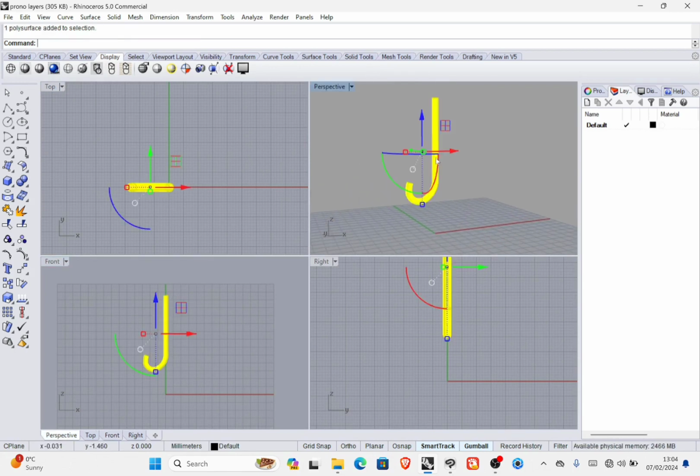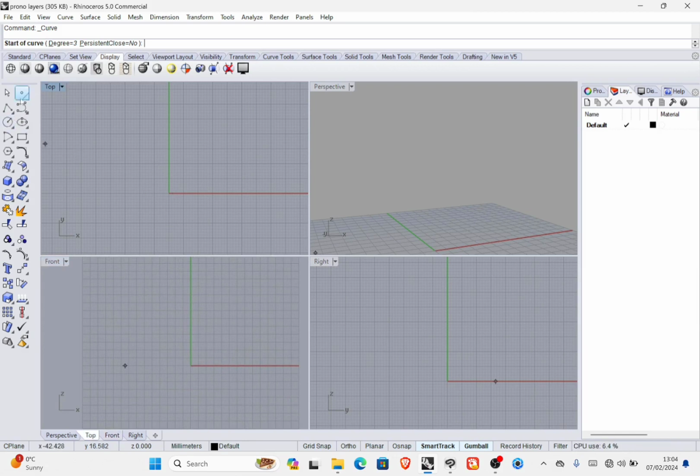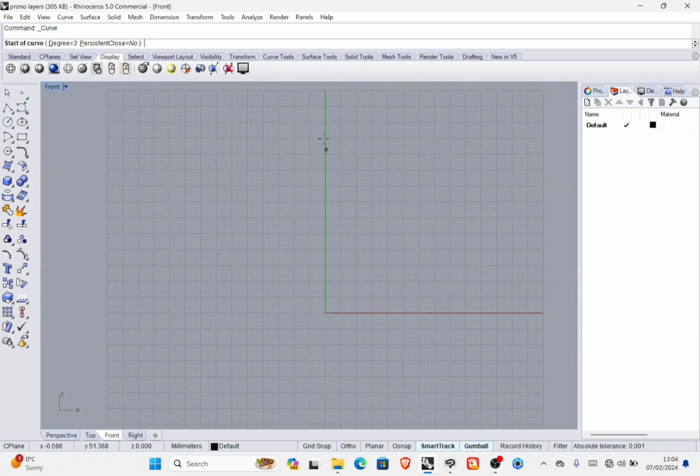So that's how to achieve a bend in Rhino. It's just as simple to use. Now the next tool we are going to use for that is the pipe tool. So the pipe tool works in this, how it works. You use the control point curve to draw the shape that you are trying to model.